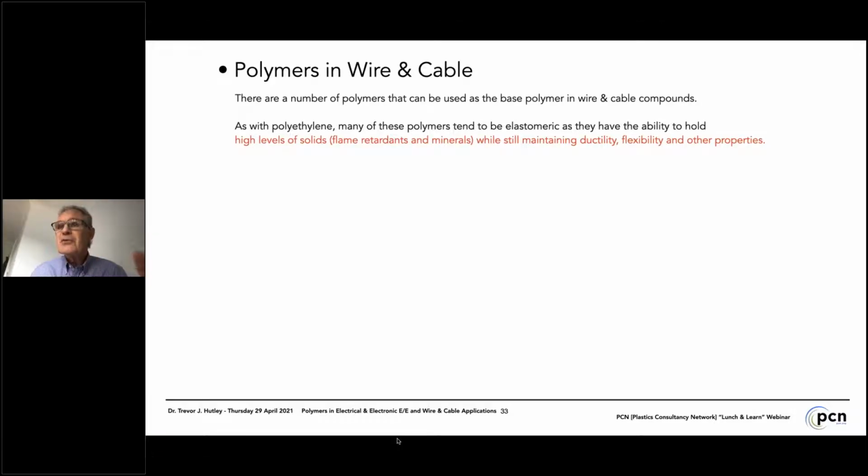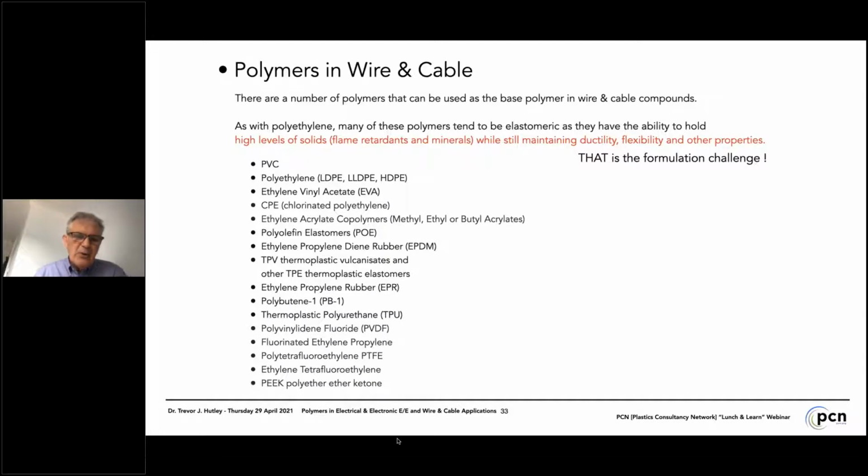We don't have the time in this webinar to go into detail of the polymers that are used in wire and cable compounds, but in general, I would say these materials tend to be elastomeric, and they have to be formulated to have high levels of solid flame retardant materials and also maintain the other desirable properties of plastics: ductility, flexibility, and toughness. And that is the formulation challenge for this particular sector. This is the whole list, so you have to look at that and study that in detail, perhaps in your own time.